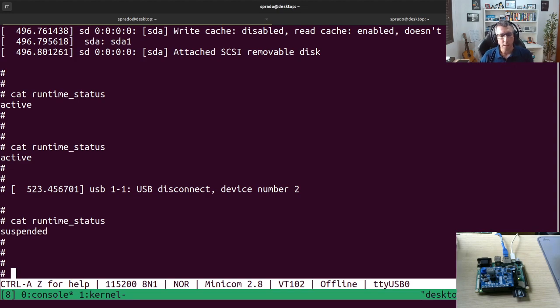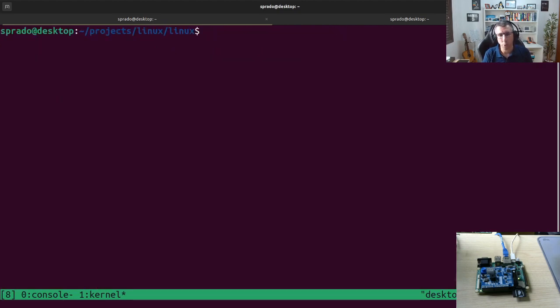For that to work, there is a concept called operating performance point. It's a combination of voltage and frequency at which the hardware can operate. This is usually defined in the device tree for ARM. If you are working with x86, it's provided by ACPI tables.